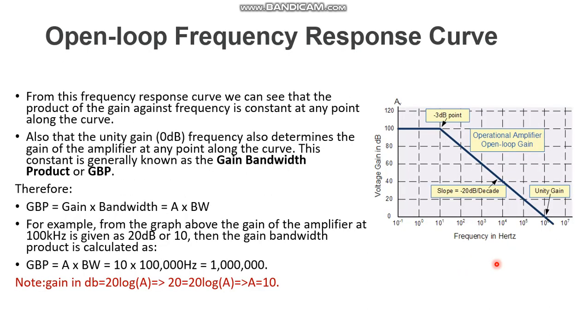Open loop frequency response. For this frequency response curve, we can see that the product of gain and frequency is constant at any point of the curve.